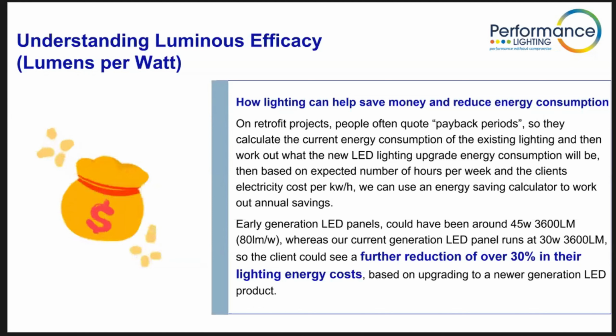Certainly most end clients looking to upgrade or install new LED are looking for the best energy saving. So that requires a high efficacy, high lumens per watt value. So the better the efficacy, the bigger the savings, the quicker the payback period. So on retrofit projects, people often quote payback period.